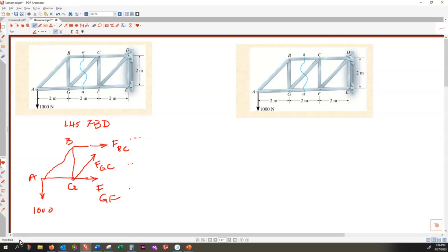If the forces are colliding at one single point, you can only solve for 2 unknowns. But if the forces are not colliding, in other words, this is a rigid body free body diagram, you can use all 3 conditions: the condition of net forces horizontally equal to 0, the condition of net forces vertically equal to 0, and the condition of net rotation equal to 0.